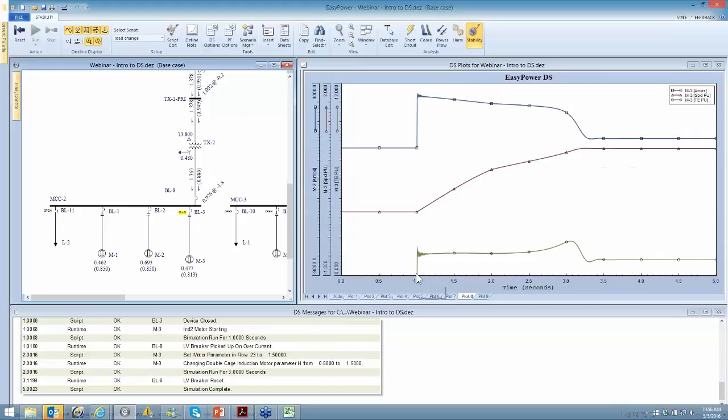All right, so again, we start with one value of the inertia, and then halfway through the start cycle, or most of the way through the start cycle, we make the adjustment there. So what we see are the current that's delivered to the motor over time. It's electrical torque that's being provided, and it's a response to that change in loading. And it's not, frankly, what I expected. So it's something of an eye-opener at the same time.